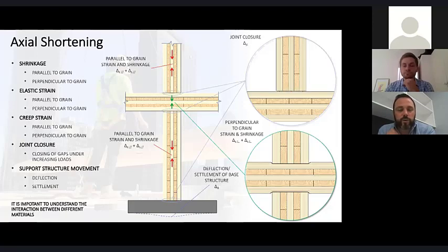A lot of people have gone down a path of these really fancy castellated connections and holes and pouring concrete into these holes to help transfer the load. It can be managed. The higher you go, the more difficult it is. But we've got an example at 55 South Bank where we've gone 10 levels, and we've been able to manage it. We've been able to calculate it. We've been able to coordinate it with both concrete as well as steel throughout the building, which is quite unique for that type of building, but it definitely can be managed.